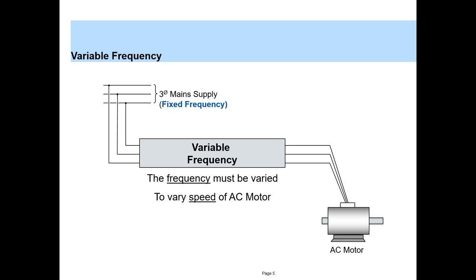What will happen is you can vary the frequency, as a result of which you can vary the synchronous speed, and hence you can operate the motor at 800 rpm. And if you calculate, in a very short period of time you will see that the cost of this extra drive is outweighed by the energy savings that you have. Alright, so in that way drives are very much useful.